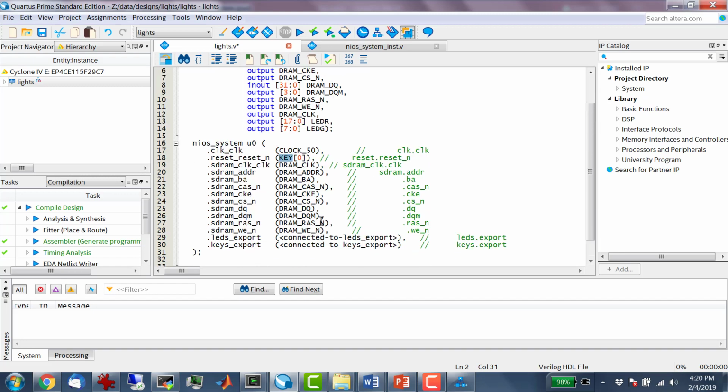And then down here, I'm going to use this Verilog convention where you can use curly braces to concatenate two signals. So I'm going to concatenate LEDR as the most significant 18 bits. LEDG will be the least significant 8 bits. Concatenated together, there will be a 26-bit signal, which will be connected to this 26-bit output, right?